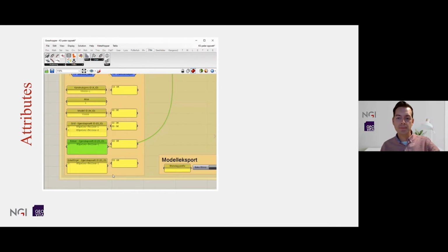Okay, early on, right beforehand, when modeling the deep soil mixing, I entered the Norwegian text in an attribute field, which I made a screen print of here. The reason for this is that this component in Grasshopper and the text are linked up to an Excel spreadsheet, which contains all of our attributes. And you might say this could also be a database. If you have tons of attributes, that would be perhaps a better solution. And this connection is, of course, also programmed in Grasshopper.